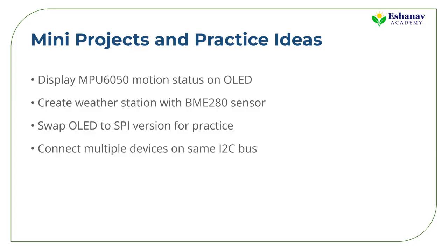If you want to see the wiring difference, swap the I2C OLED for an SPI version and measure performance changes. And for a challenge, connect both the MPU6050 and the BME280 on the same I2C bus to confirm multi-device operation. Each mini project reinforces not just coding, but also wiring discipline, scanning, and debugging, all critical habits for professional IoT